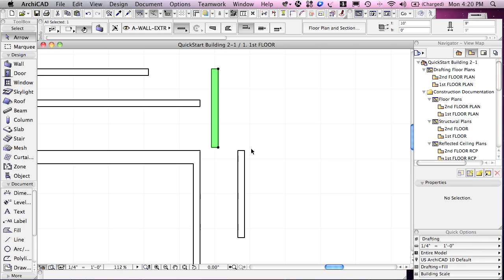Now I'm going to use the arrow tool and click to select a different wall, and I'll show you a faster way to do this. Instead of going to the edit menu, reshape, stretch, I can just press down on the endpoint that I'm interested in. With this already selected, I'll press, and while the mouse button is held down, you'll notice that there is a small palette, sometimes called the pet palette, because it used to move around on the screen like a pet on a leash, and I call it the editing palette. And you'll notice different options here.